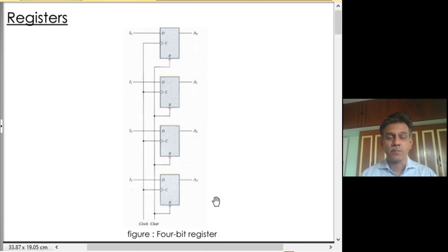These are two different terms. Sequential, because it remembers history and responds based on the input sequence. Now we put one more adjective, synchronous. We want all those changes to occur synchronously, synchronous to a clock pulse, and this will avoid the race problem.